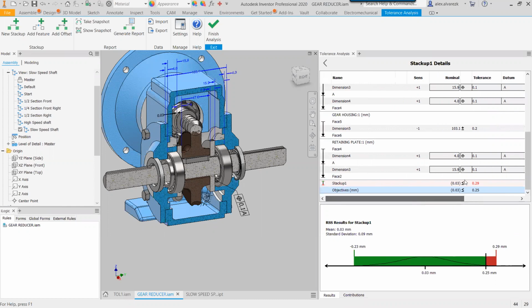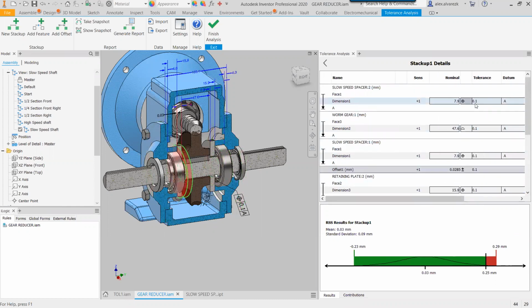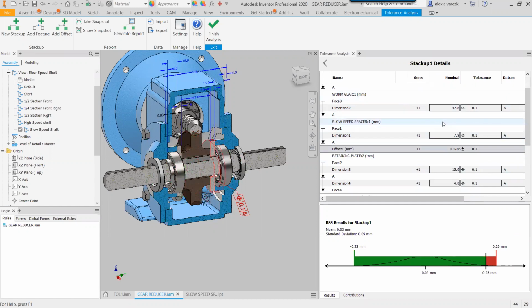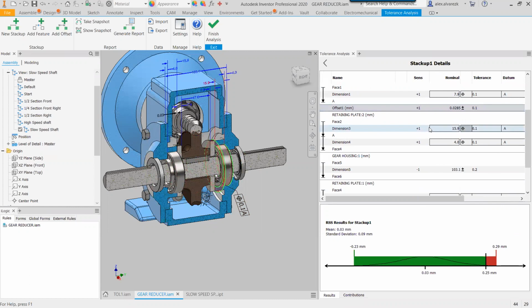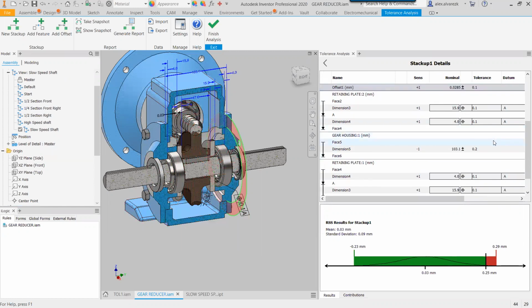Right, so what can we do here? Again, you can go back into the tolerances. You can see, maybe there's a component in here that I can change to get the tolerances a little bit tighter. That's something you can go ahead and decide. But if you're okay with these tolerances, looking at the graph, you want to make sure that this actually meets the criteria.